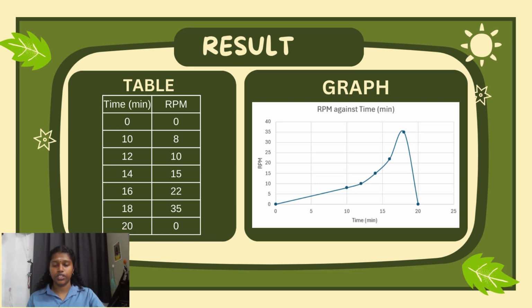Third, heat loss to surroundings. Some of the heat from the candle is inevitably lost to the surrounding air via convection. Heat can also be lost by radiation from the hot can to cooler objects nearby. This unwanted environmental heat loss reduces the heating rate of the water. Minimizing exposure to air currents and using a contained heating setup could help.